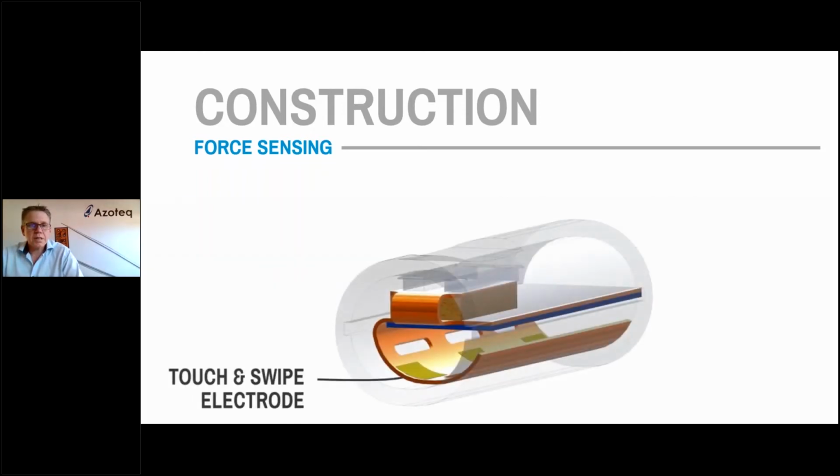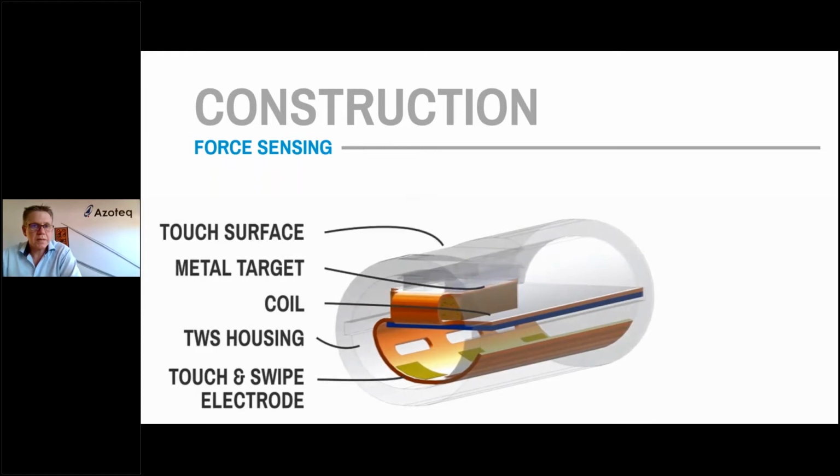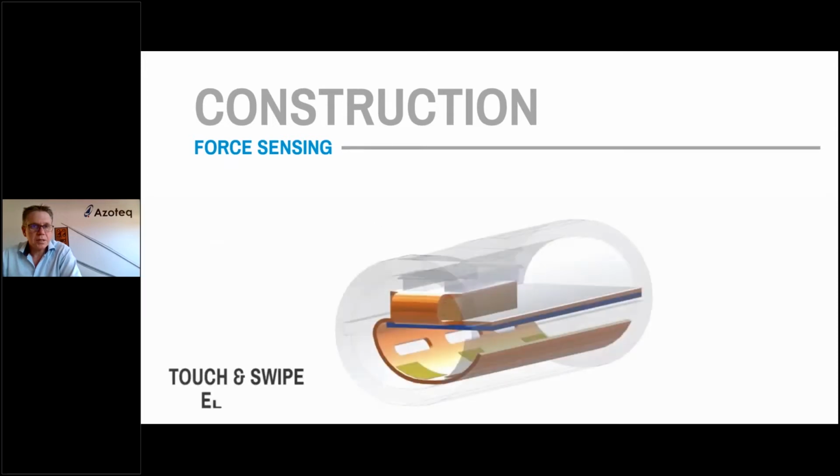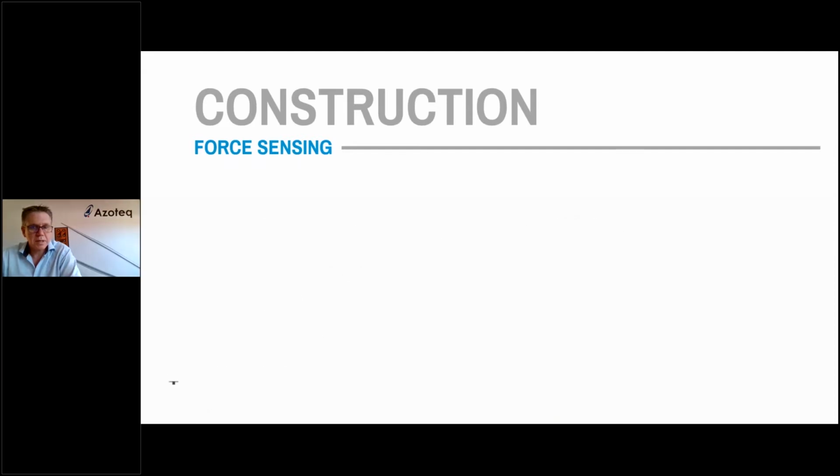On the screen is just an alternative idea to measure the force sensing. So in this instance, the force is applied in the Z direction, and we have the metal target kept in position by spring foam type material, and we measure that small deflection with the inductive coil.